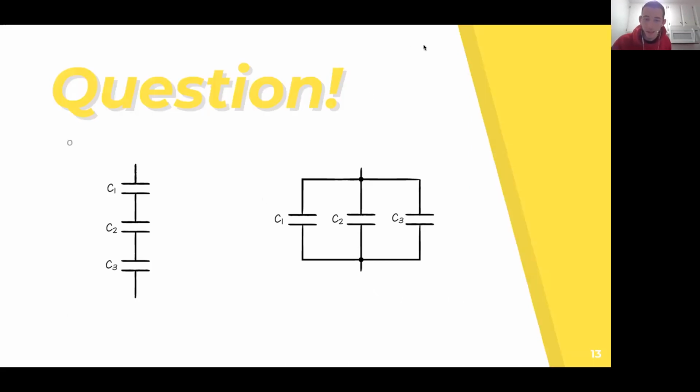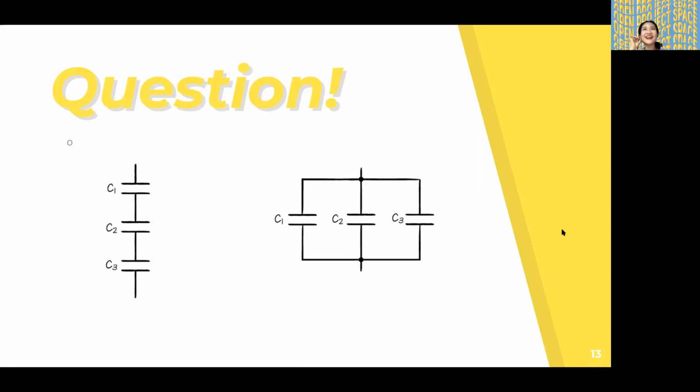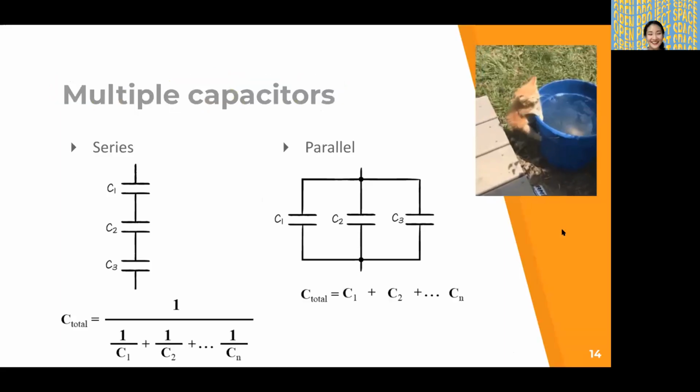Okay. So when you've got a capacitor, its capacitance is inversely related to the distance between the two plates. So when you put multiple capacitors in series, you're effectively increasing the distance of a single capacitor. It's essentially like having one capacitor that has the distance equal to the sum of all three capacitors in series. That's good. I like that.